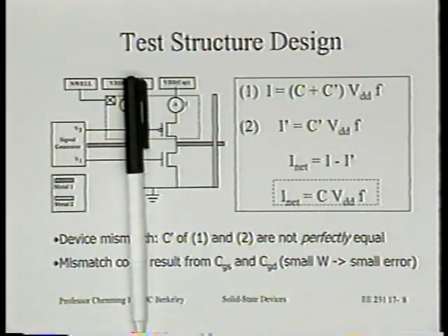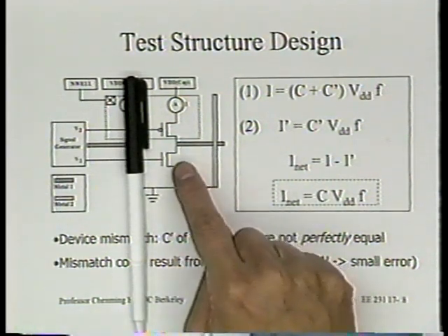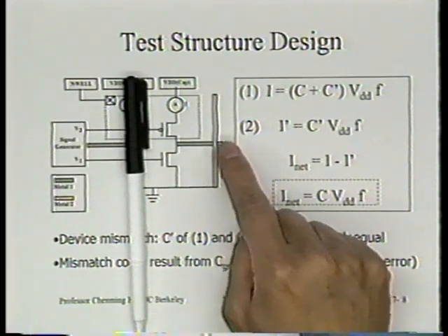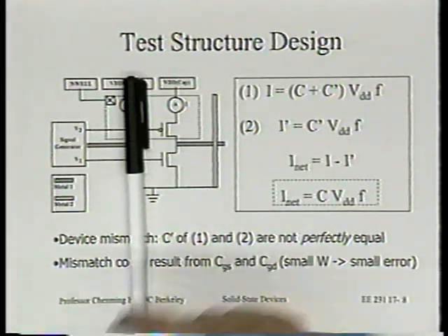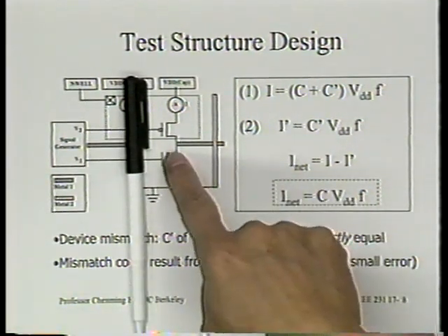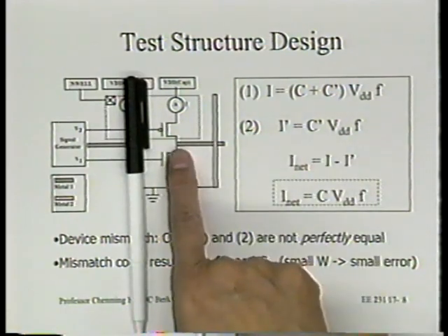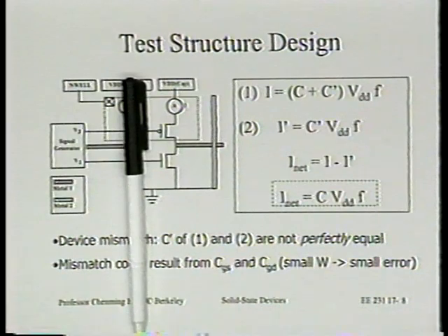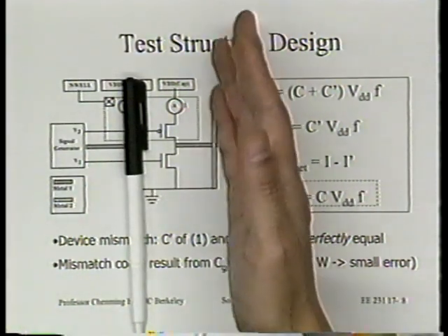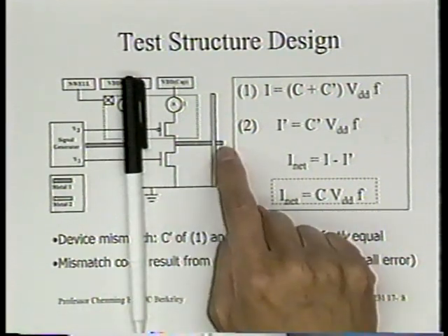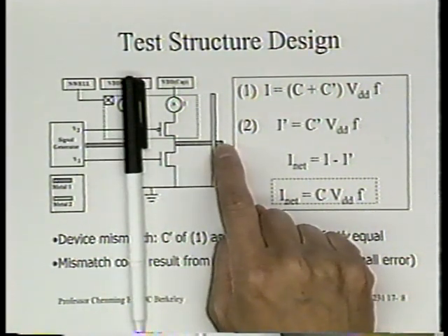And the only load that this test structure has is that small capacitance you're trying to measure. Here I'm drawing this metal 1, metal 2 crossing as an example. Think of this as metal 1. It's connected to the output of this quote-unquote inverter-like circuit. And the vertical line is the metal 2 line connected to ground. So the load is just the capacitance. You see that?